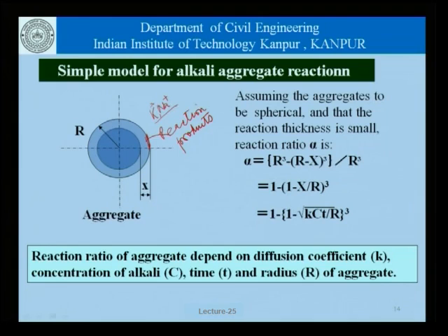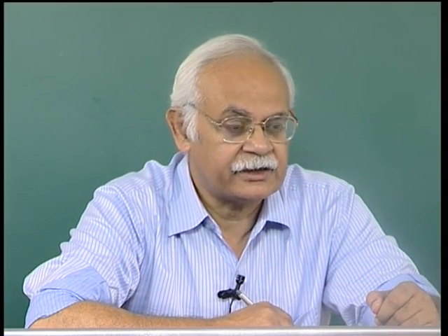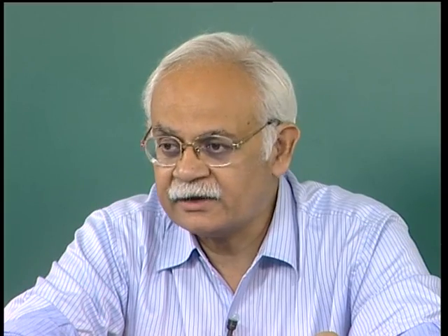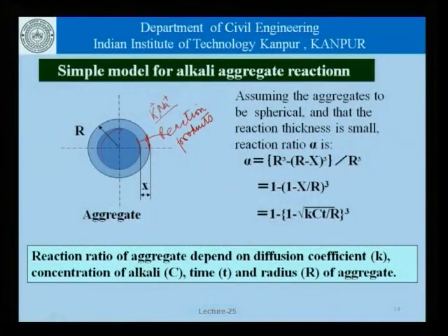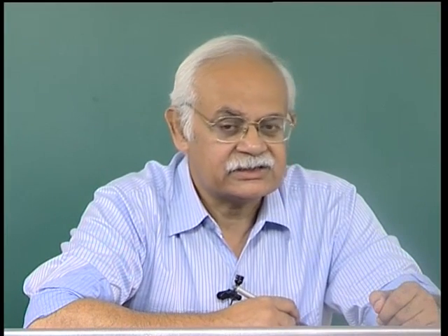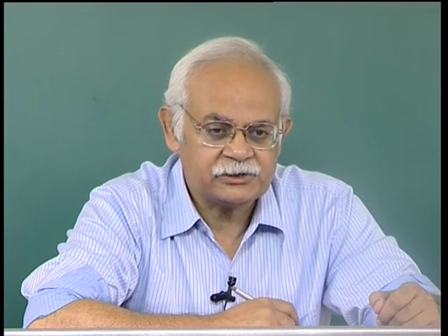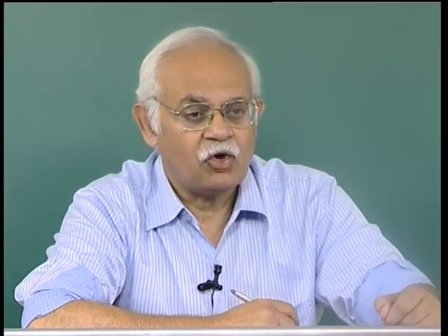After that deposition has taken place, for additional surface to be attacked, if this reaction thickness, or the thickness of the aggregate which has been compromised, or where the reaction has already taken place and the aggregate has undergone the alkali aggregate reaction, this part is still unreacted. So, basically at each time step the reaction occurs at a fresh surface of the aggregate, and the surface of that reaction keeps shifting inwards. So, now over a period of time,